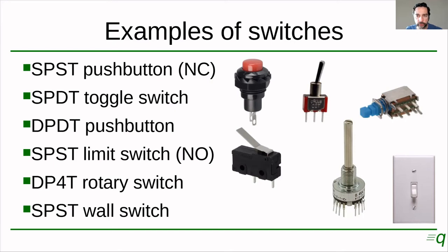So this switch has 4 positions. It's printed here, C1, that would be common 1, and then position 1, 2, 3, and 4 over here. The C2, it's the common for the other pole, and it's going to have positions 1, 2, 3, and 4.